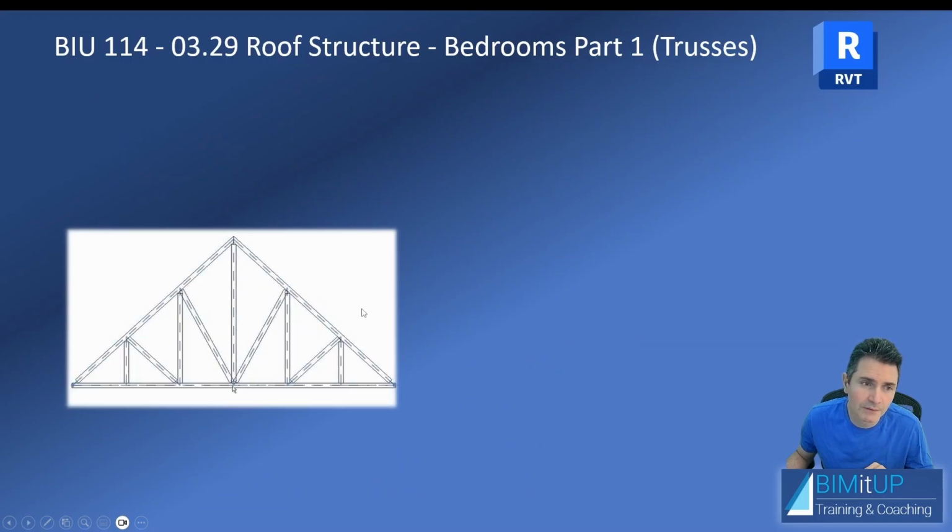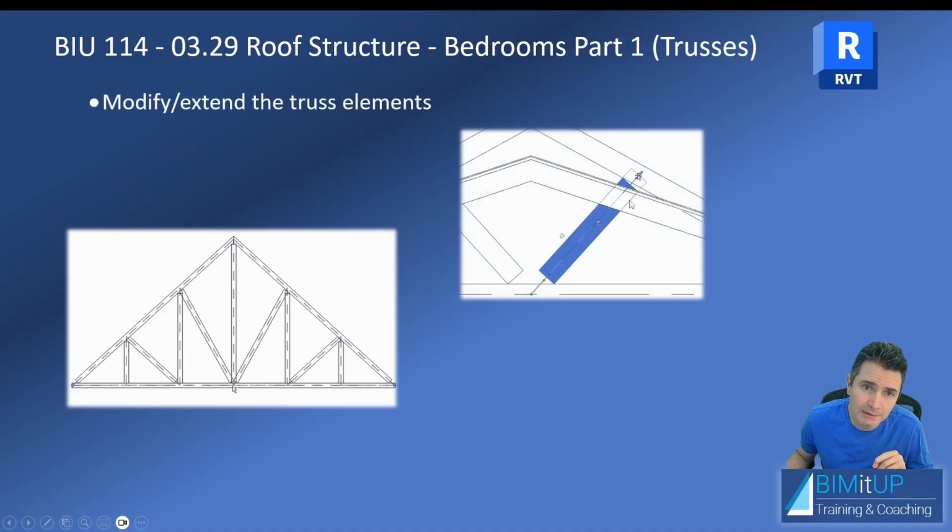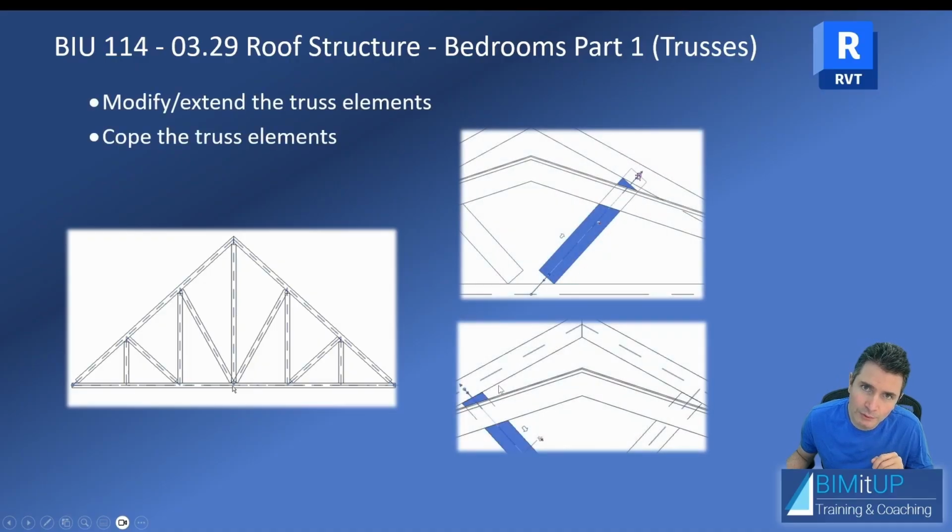We're going to focus in this video on how to edit this truss system. It's going to be really nice because we're going to extend the truss elements, and then we're going to cope the truss elements so that it trims nicely against the rest of the structure. And then we're going to accurately adjust the elevation of the truss system.